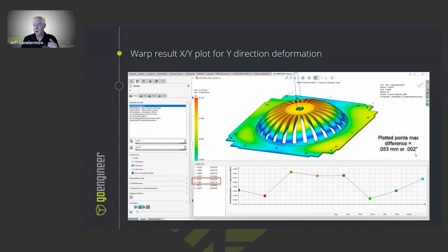Remember when we started this, we were probably closer to almost 10,000. So reducing our wall thickness, making it more uniform, working with our cooling channels, all of those things to get an accurate result. I think if we think of the word that actually works the best is uniform, right? You want uniform cooling, you want uniform wall thicknesses, uniform pressures, uniform fill time. All of those things go together to make a really good plastic part.